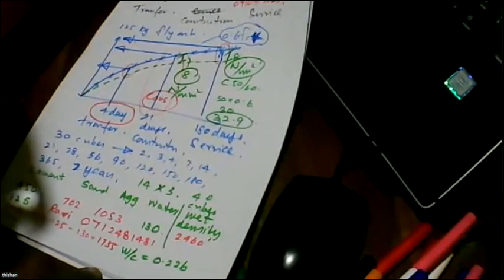So that's the way we have to look at the use of high strength concrete. If you say I'm going to achieve 60 megapascal in 28 days, it's totally unnecessary. Rather than doing that, you can easily introduce an extra calculation layer, that is the construction stage. What is going to happen during construction? As long as the beam is strong enough to withstand the stresses at the construction stage.